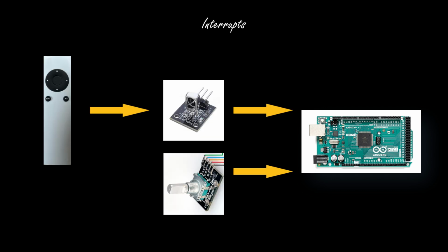Arduino microcontroller has a very interesting feature, like the majority of computing systems, which is the interrupts. I can configure Arduino in order to accept interrupts from the outside world. In my case, I can define some digital pins within Arduino which will trigger interrupts.